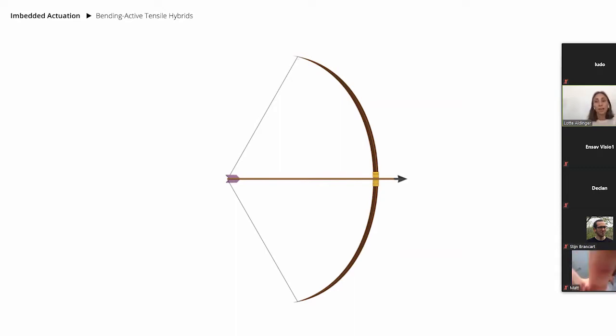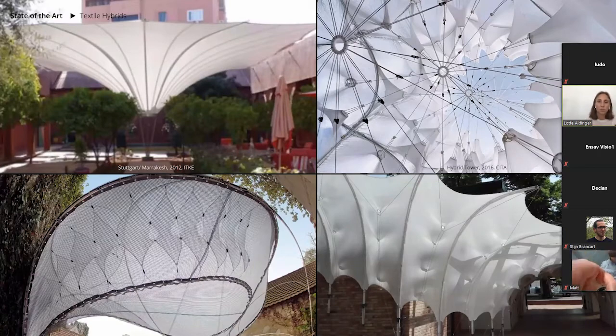And taking this further, with combining it with membranes, this can have beautiful shapes and local articulations, and it's a really powerful way. However, it has challenges because it's not unlimitedly scalable, and at the same time, it does not react very strongly from an engineering perspective to external loads, because of its low stiffness that is required for the formation.